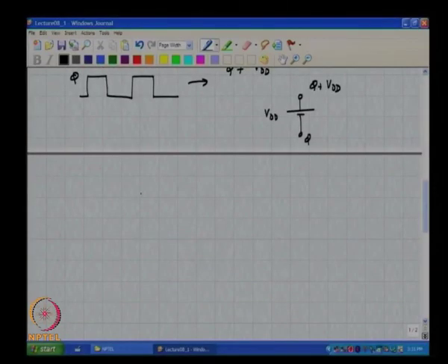And so, if there was a capacitor and this end was tied to phi, when phi is 0 or when phi is low, the capacitor must be charged to VDD. So, how will you charge this? And by what signal must the gate be controlled? When phi is low, this switch must be open or closed? Closed. So, it must be high, it must be closed when phi is low, which means that it must be controlled by phi bar.